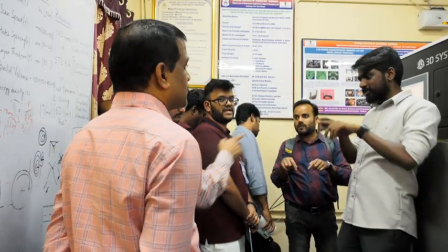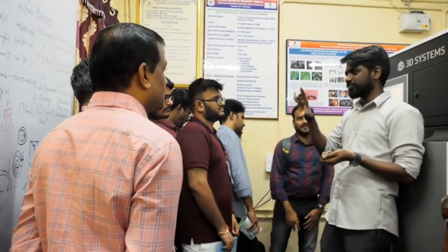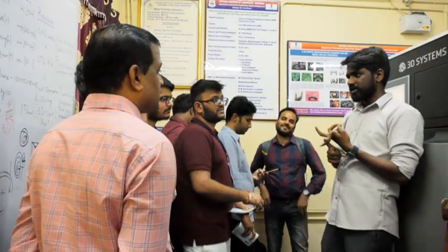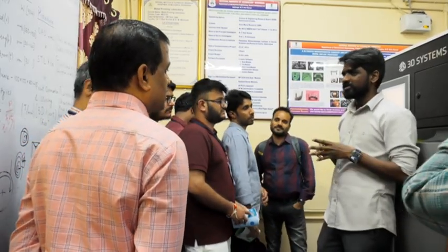If you are having a build platform of 10 by 10, you need to fill it: 10 by 100 into 8. That means 10 centimeters, 10 centimeters, 8 centimeters. So that is the minimum quantity of powder. That's the base build volume.